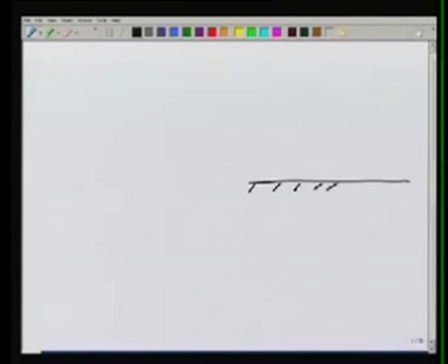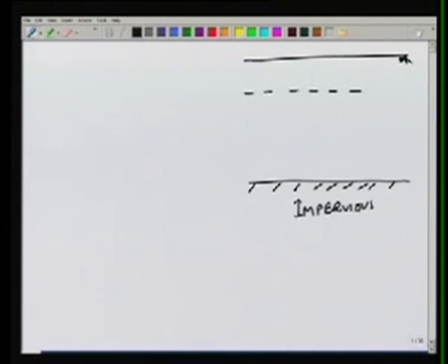Compared to this, the unconfined aquifer doesn't have an impervious confining layer at the top. So if we look at an unconfined aquifer, there is a layer at the bottom which is impervious, and then the ground level. The unconfined aquifer, the groundwater table would be open, and therefore the pressure on the top of this will be 0 or atmospheric.